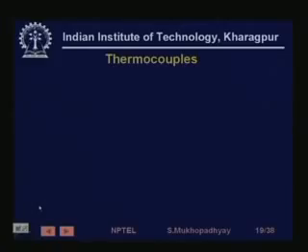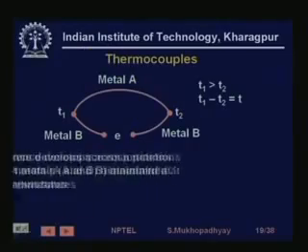So here are these two resistive sensors. One is a metal resistance, another is semiconductor resistance, and you basically use Wheatstone's bridge, and they have trade-offs regarding sensitivity, linearity, range, etc. After that we come to thermocouples, which are based on the principle that if two metals,